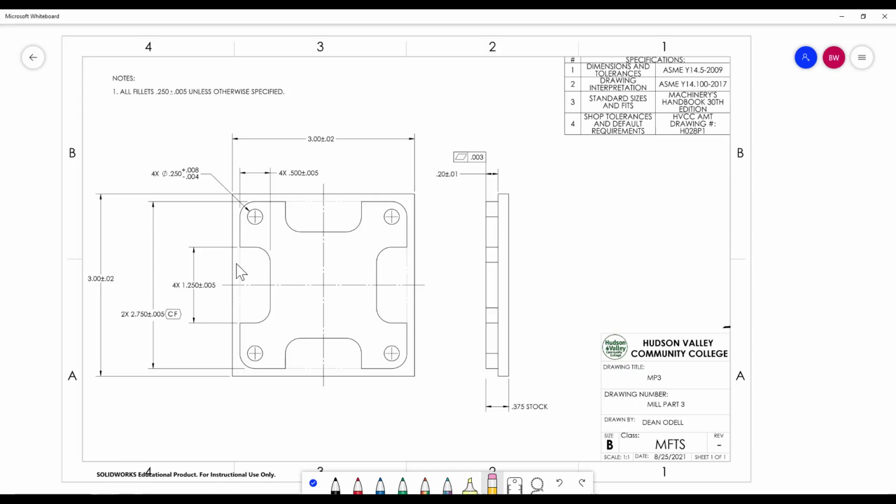And again, 2.75 divided by 2 is the outside of the workpiece, 1.375. Okay, so we're right here, compensated. So we need to go now up to this position. Okay, right here. Okay, so 1.375, since it's a square, it's kind of nice. So we're going to be going to a Y position. Okay, we took care of the X, we're right here.